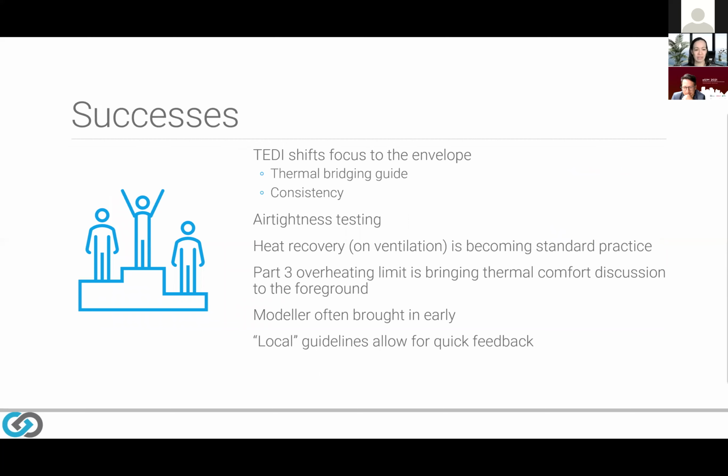So on that note, what are some of the successes that we have seen thanks to the step code? Well, as I was just talking about, the TEDI really has been shifting focus to the envelope, and shifting those conversations to the envelope as well. The thermal bridging guide, like I mentioned, has given us a consistent way of evaluating thermal bridging for energy models. Also, for those of you who aren't aware of the guide or haven't used it before, the appendices provide hundreds of pages of typical details and what the values would be associated with the details.